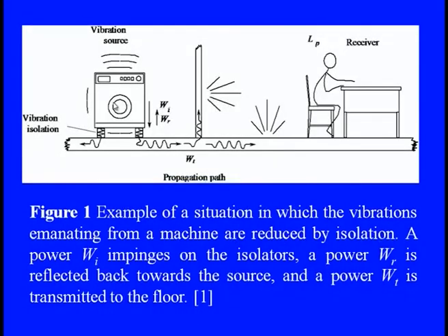So, you see here through this isolator feature some part is being absorbed and repelled back towards the source, some part of the energy is transmitted through the ground, and even by putting some kind of obstruction in the path, it can also provide some kind of media through which the vibration transmission can be featured out. So, ultimately when it is reaching the receiver, the path of this vibration transmission is so deviated that the vibration frequency and the amplitude and the sound level, the sound power level or the energy, is almost reduced by various ways.